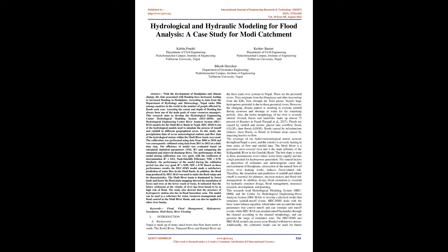The efficiency of the model was evaluated based on calculated statistical parameters, NSE, R2, and comparing the simulated and observed discharge flows. The performance of this model during calibration was very good, with the coefficient of determination R2 equals 0.81, Nash-Sutcliffe Efficiency NSE equals 0.78. Similarly, the performance of the model during the validation period was also very good, R2 equals 0.80, NSE equals 0.78. Based on these performance results, the HEC-HMS model made a satisfactory prediction of water flow in